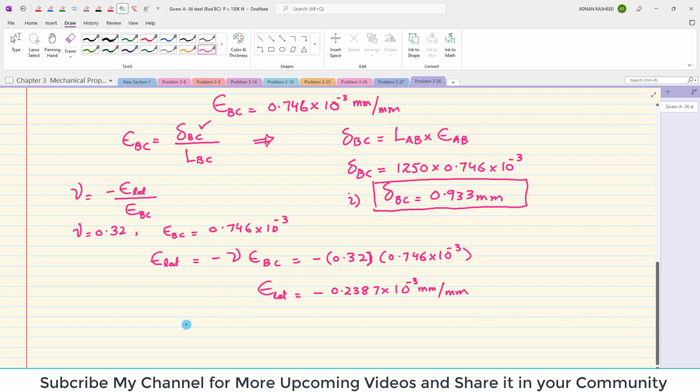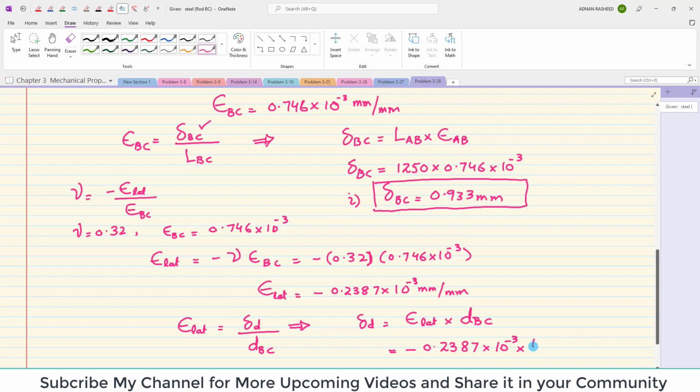Now this is the lateral strain. From this lateral strain we will find the change in diameter. Since this lateral strain is equal to change in diameter divided by original diameter, and original diameter is the diameter of BC, we can get change in diameter equal to lateral strain into original diameter of the rod BC. So minus 0.2387 into 10 raised to power minus 3 multiplied by original diameter of rod BC, which was 40 millimeter. So this is the change in diameter.